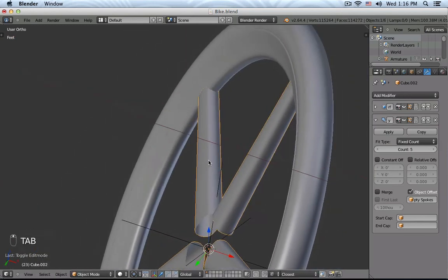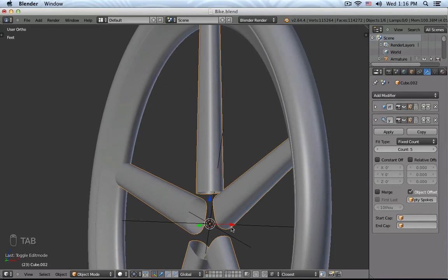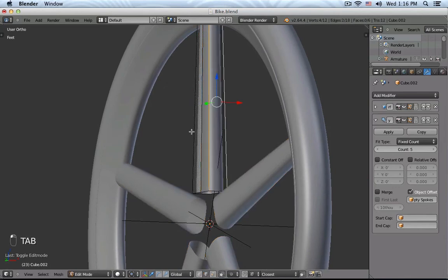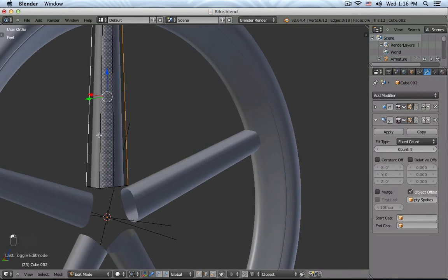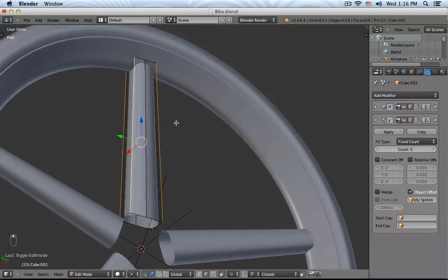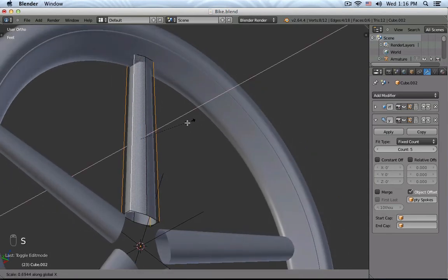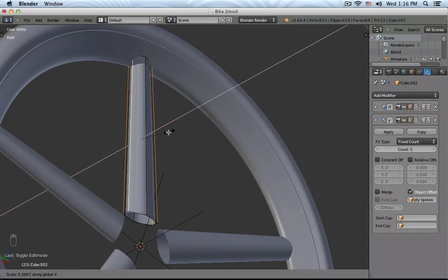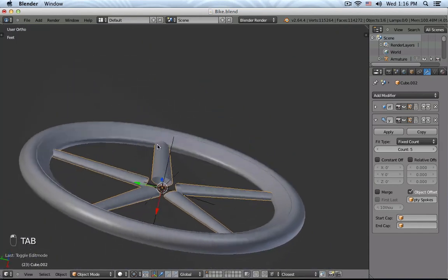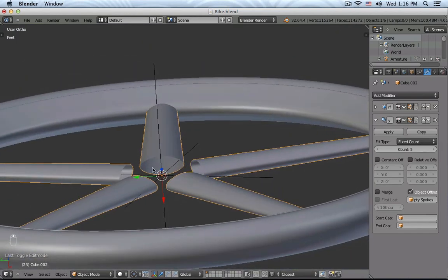So now it's a little bit flatter. And you see that those other elements are like clones. They're interactively created for you. I could select those 2 pairs of edges on each side, press S and X, and scale it along the x-axis. So I create kind of like this cross section.